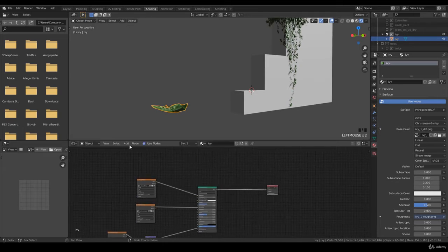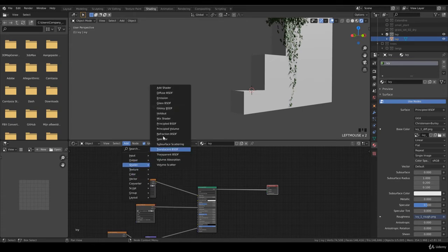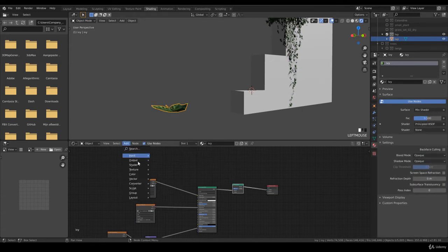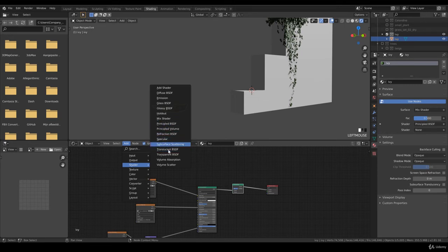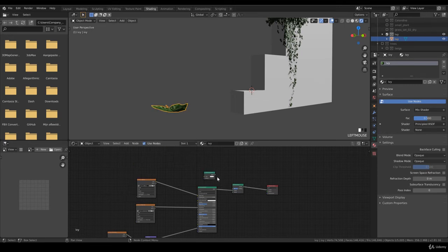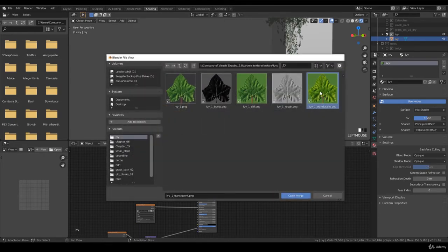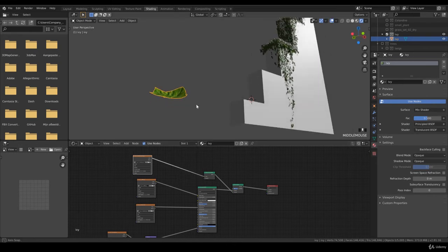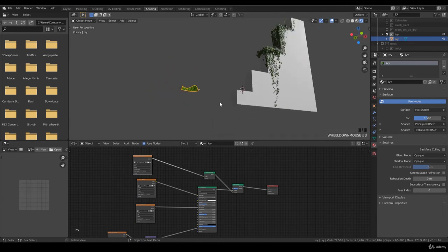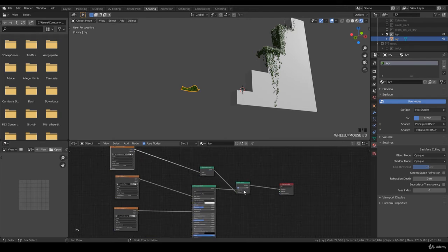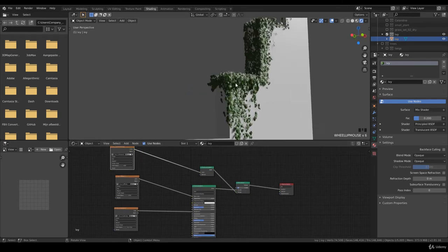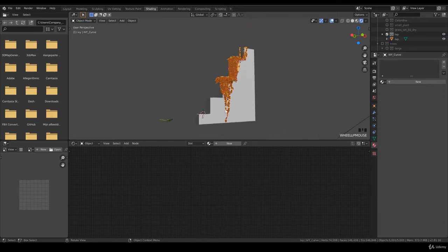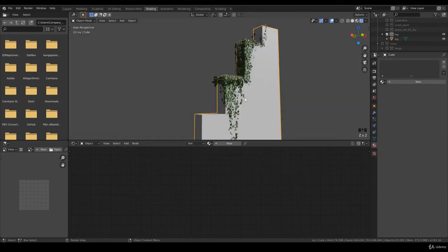And let's drag this one, go to add shader, mix shader, and add shader translucency. Yeah, putting it right there. And I want to duplicate it and go for ivy. There you go. Pretty good. Looks wonderful. So now you only have to change the value of the translucency to 2.2, and that should be applied now on the particle. Solid, render it again. That's great.